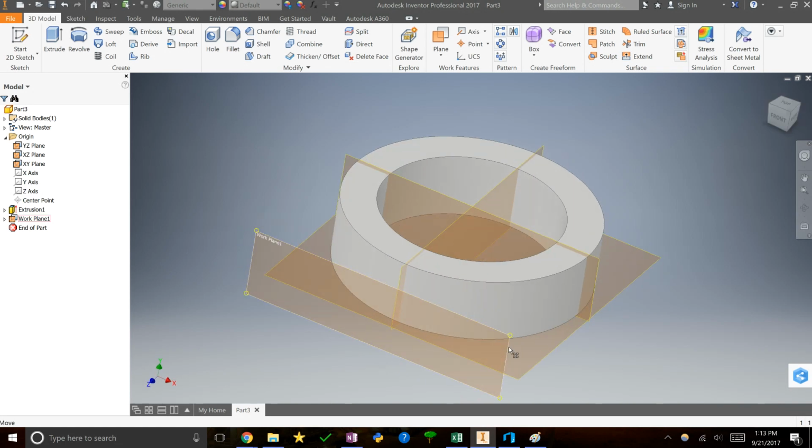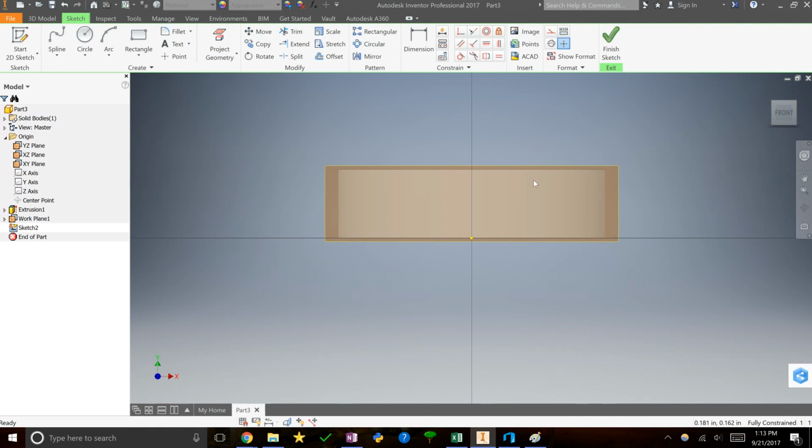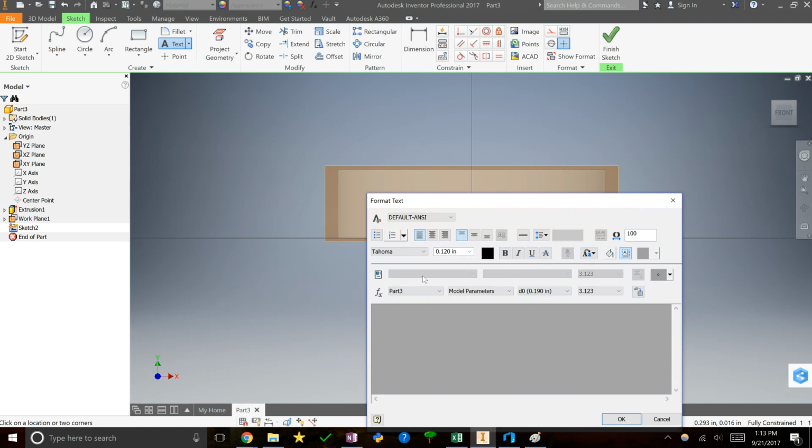So we're going to make a sketch on here. So you click it, and then you hover over. Oh, you don't want to do that. Click Create Sketch. There we go. All right, so now we're going to put some text on here. So I'm going to go over to Text and just drag a big box out. All right, so the text is kind of annoying, Inventor. I'll show you the little quirks it has. I'm just going to write...